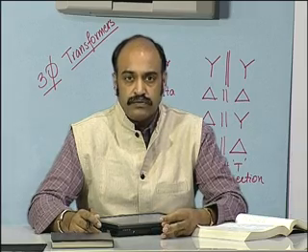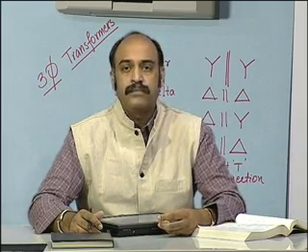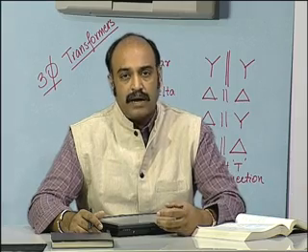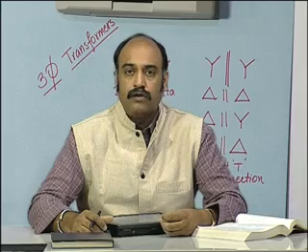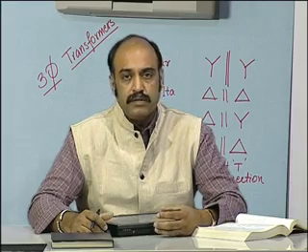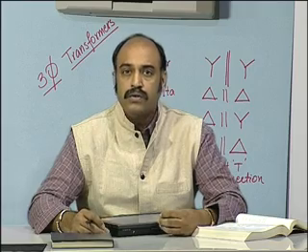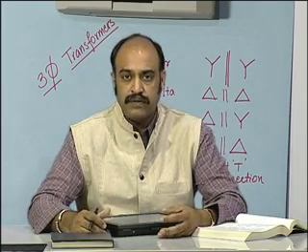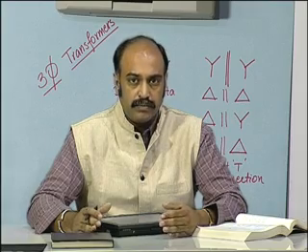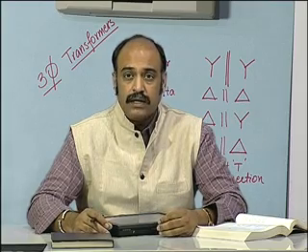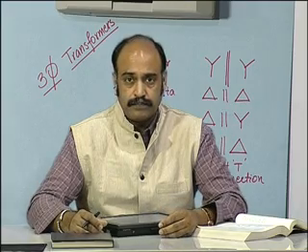The Faraday's laws of electromagnetics, that is E is equal to n d phi by dt, the Ampere's law, and all the notions of leakage inductance, the mutual inductance, the core loss, the hysteresis loop, all those concepts that we studied in the single phase transformers are equally applicable to the three phase transformers also. In fact, the equivalent circuit will also be similar.